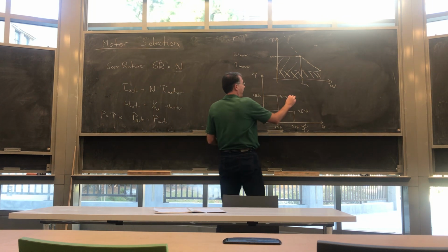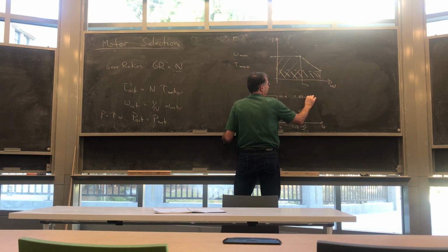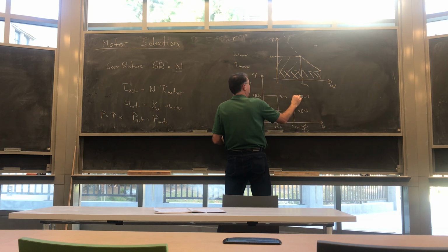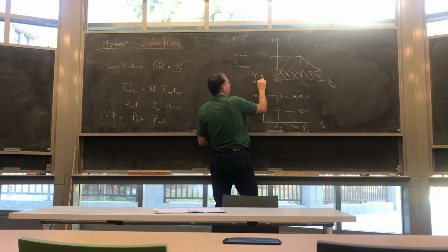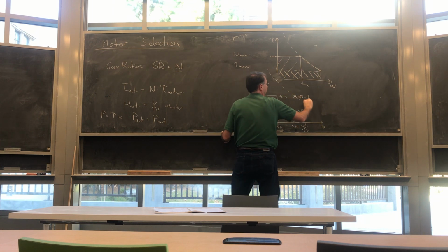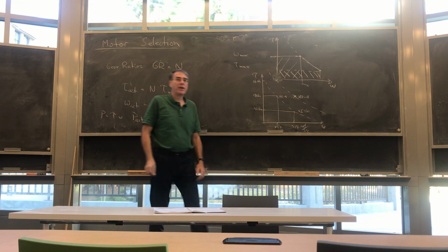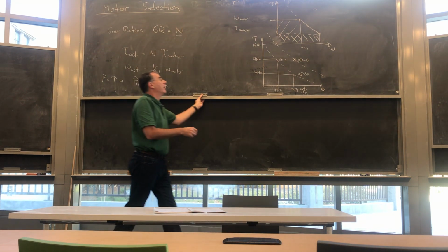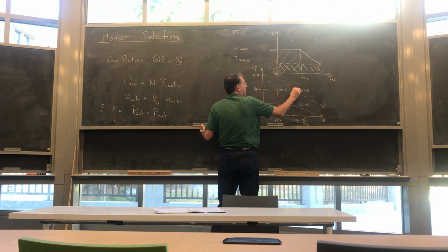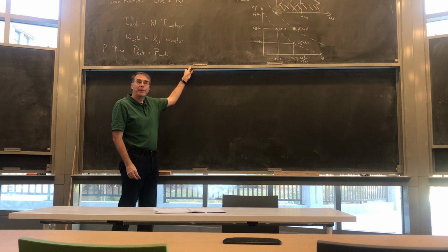And then we have an X8, I think it's called 8, though they say it has 9 Newton meters, which is this one. I'll get rid of that. And a 16 Newton meter, which is this one, right? So the X8 lies on a higher power curve than the X5 does. One of the things I'm going to ask you in the homework is, of those 4 motors, which ones are you going to put where? And obviously the big ones are going to go at the bottom.